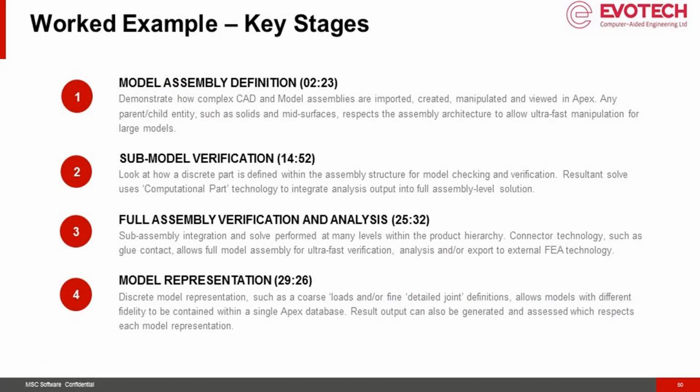In this worked example, we'll go through a number of key stages. Stage 1. Model Assembly Definition. We'll demonstrate how complex CAD and model assemblies are imported, created, manipulated and viewed in Apex. Any parent-child entity, such as solids and mid-surfaces, respects the assembly architecture to allow ultra-fast manipulation for large models.